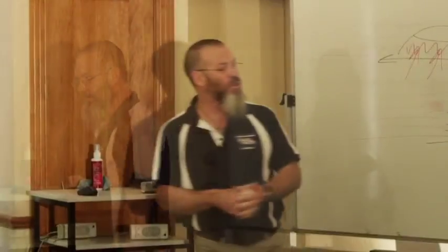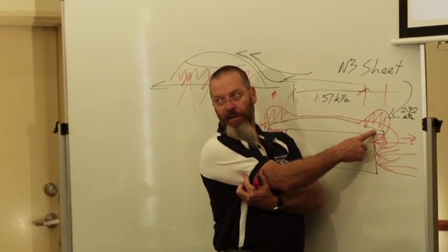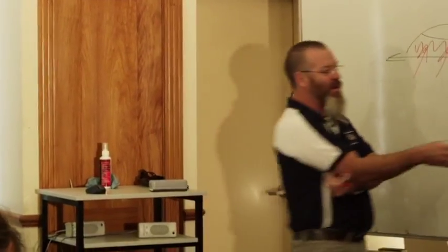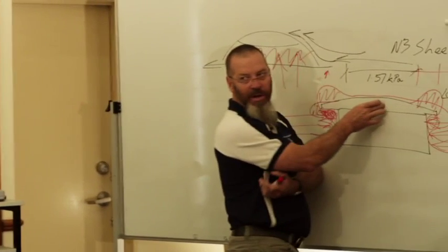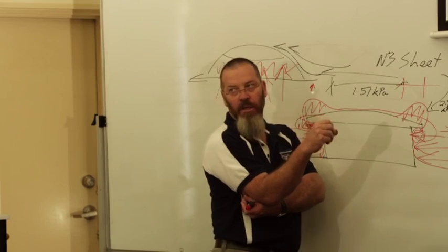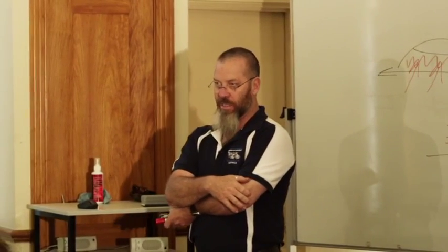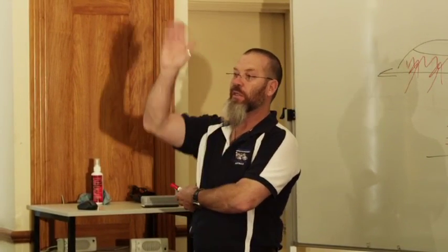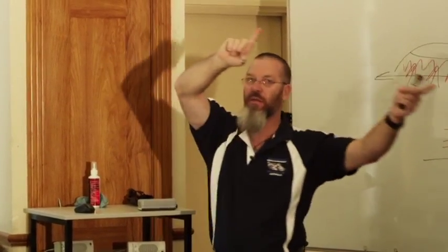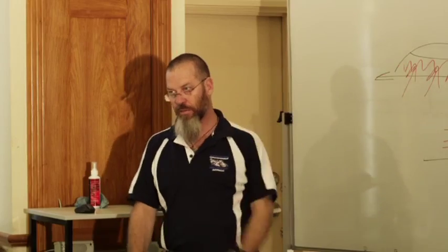And you can thank Dr. Bernoulli for that. If you think about it, the area surrounding a batten connection out here, let's say our battens for a tile, for a sheet roof are at 900 centres, okay? They're 900 centres over here in the edge area, and they're at 900 centres over here. So the area is the same, okay? You will get some cases in some industrial buildings where I actually was standing at the Big Green Hardware store the other day, and I looking up at the purlins on the roof, and over towards the edges, because they had them out here at 1.5 metre centres, over on the edges they had them at 750 centres. Thank Dr. Bernoulli for that.